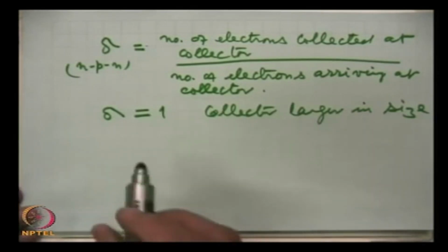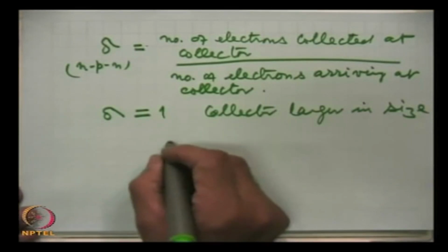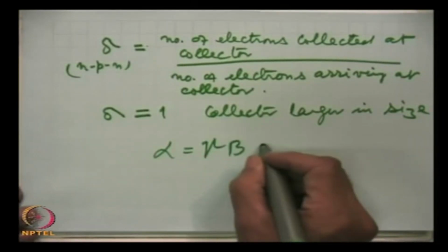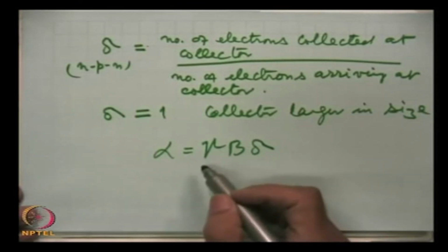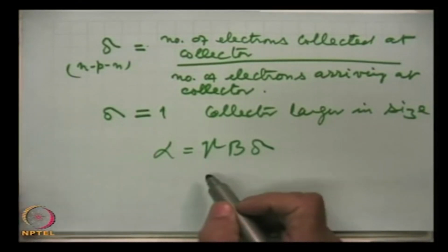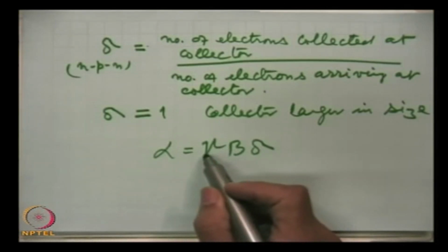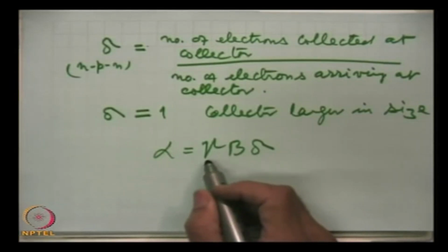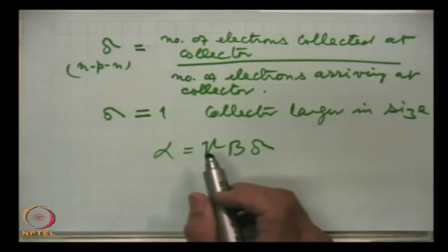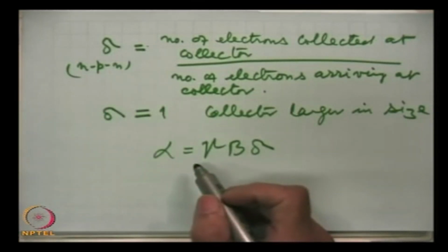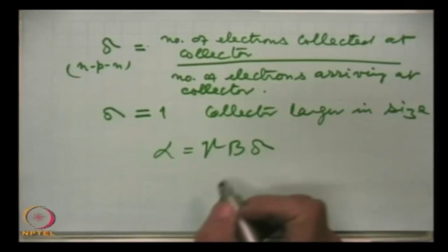So, in summary, in an efficient transistor, alpha is composed of 3 components, where we have talked that the emitter efficiency can be obtained closer to 1 by making the hole diffusion in an NPN transistor less, that means by doping the base lightly.